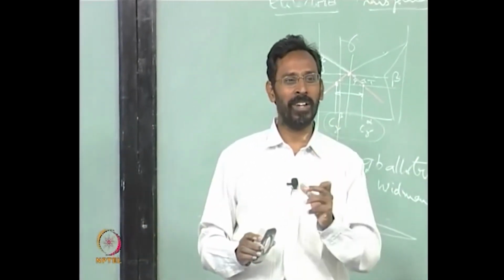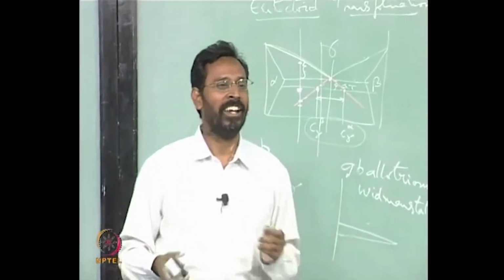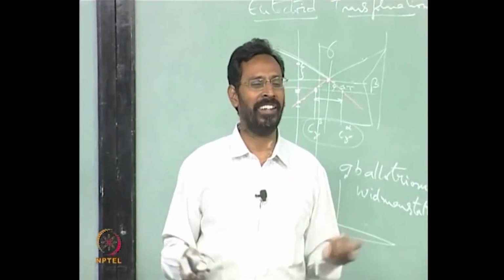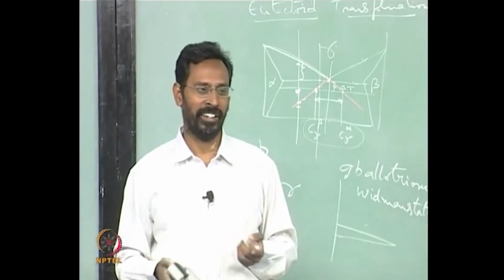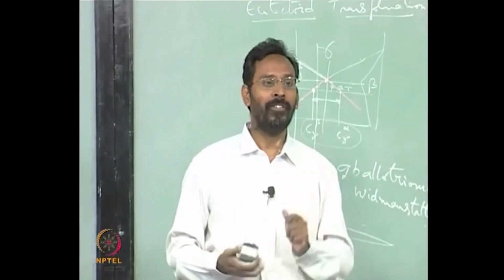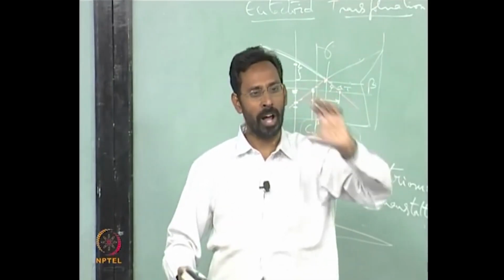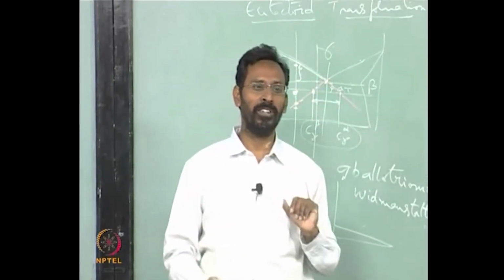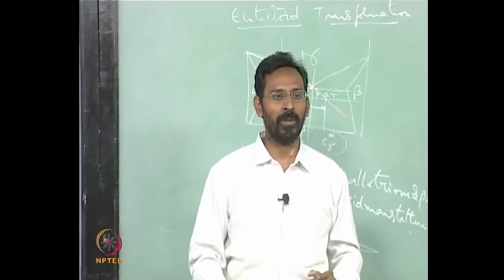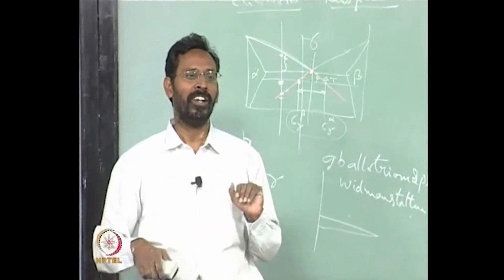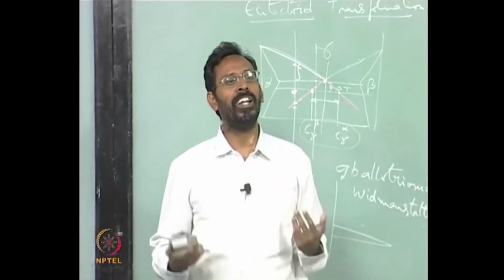So in principle a bainite can be called a eutectoid. It is only semantics, it is only how you look at it. But if you look at the whole transformation, first the gamma is giving you alpha of the same composition, which is a polymorphous type of transformation, and from the polymorphous transformed alpha, cementite is precipitating out.